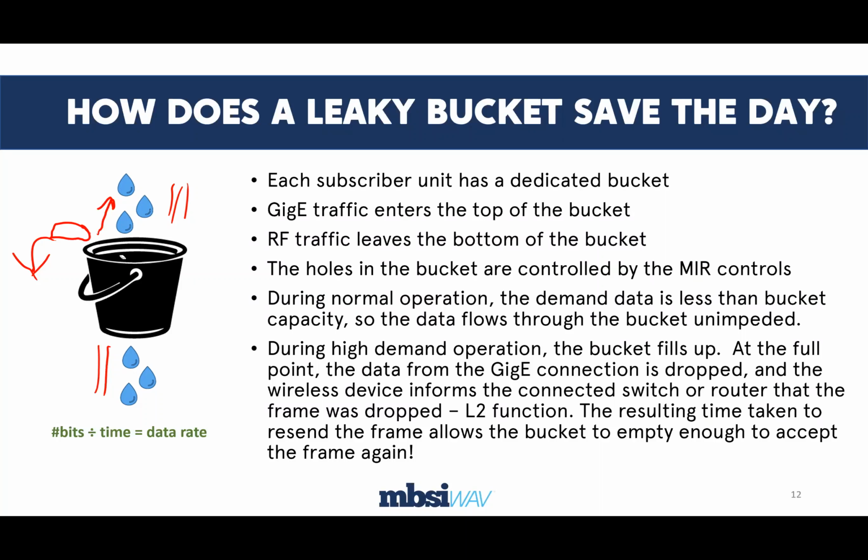This is how the maximum information rate algorithms work in almost every bit of broadband equipment, from every manufacturer out there, in some way. They'll call it tokens. There'll be different ways of actually making the MIR operation work.